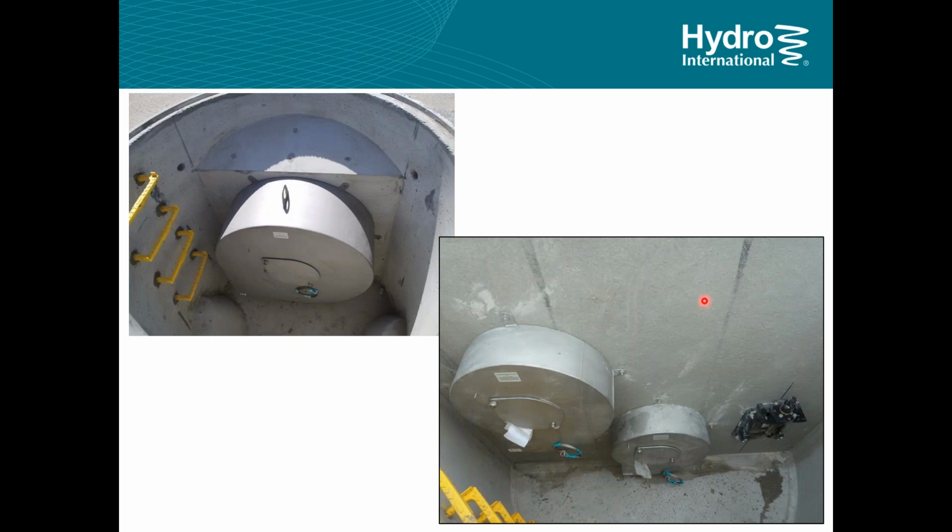Mounting, when you mount these valves, as I said before, every valve is a custom build. We tend to build them for a structure. The most common is a flat mount. In Chicago, this is a fairly common detail where they'll cast in or grout in a flat spot for the valve, although the valves can be made with a curved mounting plate that would go hard up against a manhole structure.